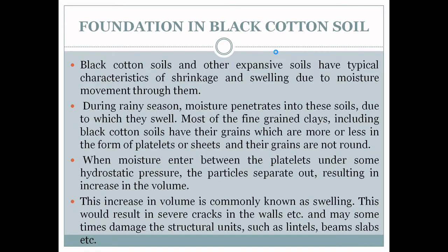Next topic, foundation in black cotton soil. Construction of building on black cotton soil or expansive soil is very dangerous due to its volumetric change with the change of atmospheric condition. When the black cotton soil becomes wet, it will swell excessively, and when it becomes dry, it will shrink excessively.